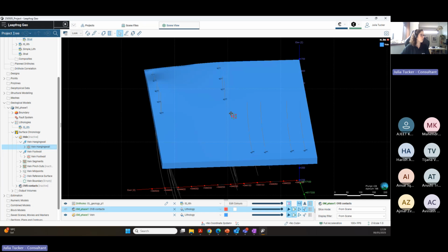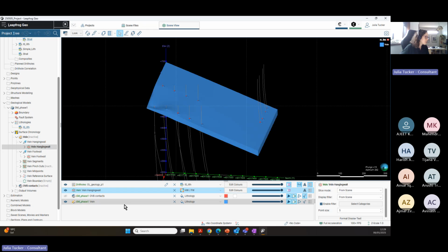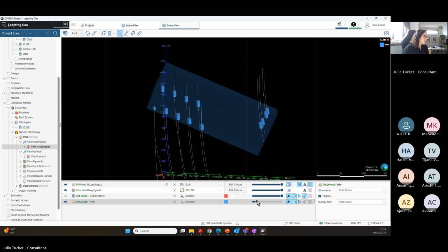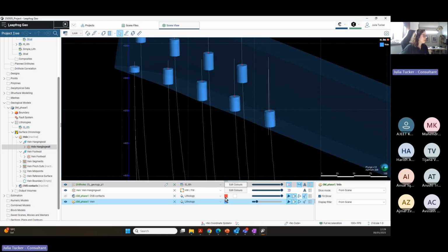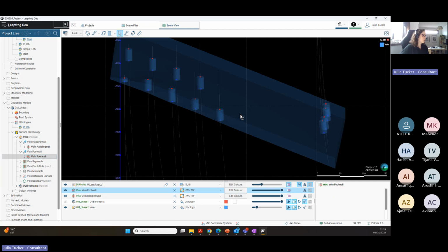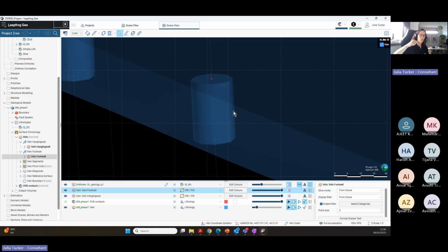And one thing that I wanted to visualize is this. Let me just put a bit of transparency on the vein. Why? Because this way right here, we can check how the program is setting the hang wall and the footwall. So if we input right here, the footwall is on blue and the hanging wall is on red. So red on top, blue down. Remember that the on top is not necessarily physical on top, it's the geological on top.